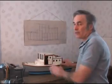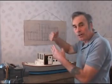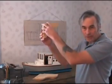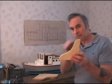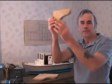And where two framing pieces come together, like a rib and a floor timber, or a cabin frame and a cabin beam, we have what we call knees. I use a gusseted knee. This is the actual knee piece itself. It's a typical boat knee. I call this a hanging knee when they're up above supporting a cabin deck beam. The ones down in the bottom connecting the ribs to the floor timbers, I don't have cut like this. I just have them straight sided because they're easier, and for strength they look a little nicer, and also they'll give you clearance so you don't hit your head on them, the cabin beam.